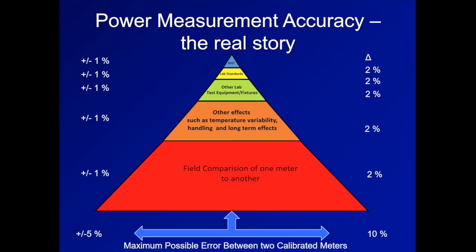And if you read the specifications for most analyzers, what's the measurement uncertainty? It's that familiar 0.05 dB, so it's another 1%. So now we're up to 3% error, perhaps. In other words, that's the maximum delta that you might have. But we're still not done.